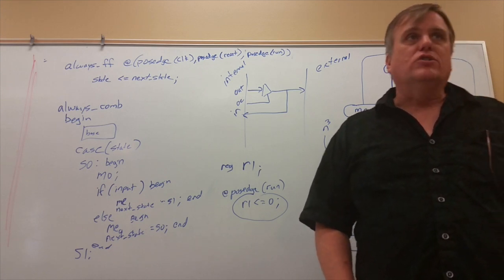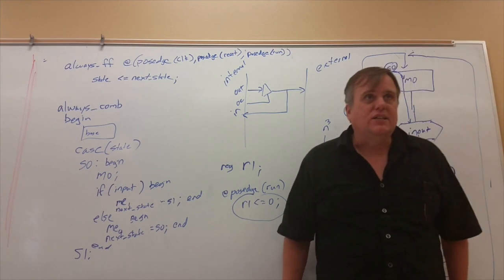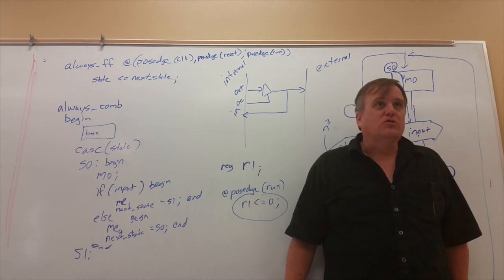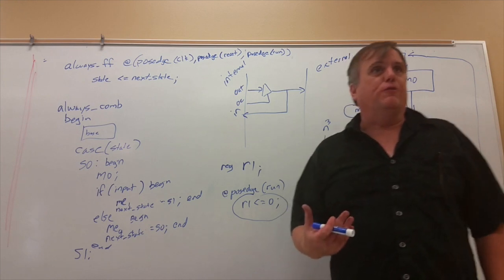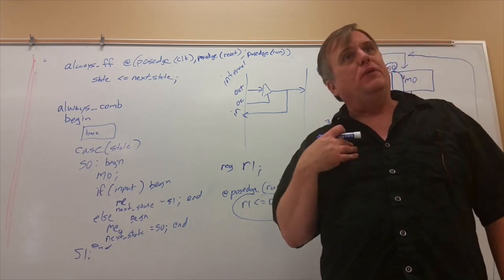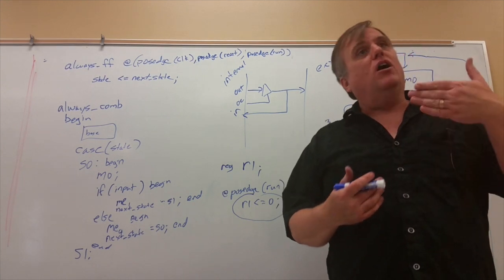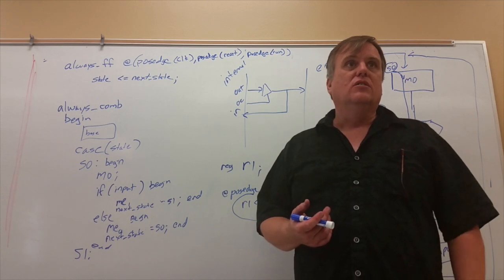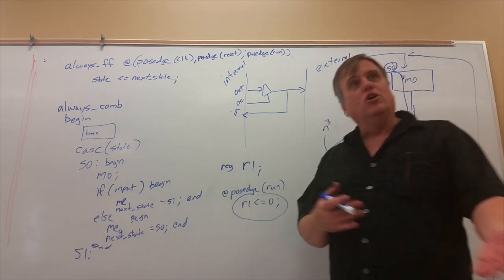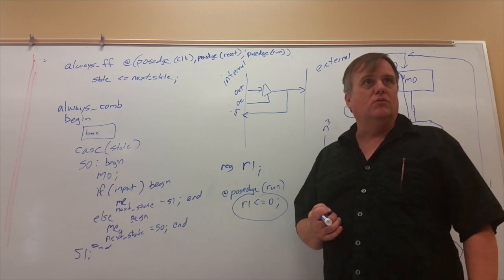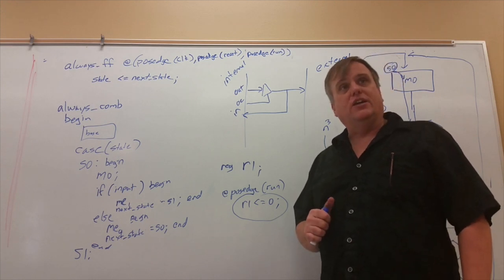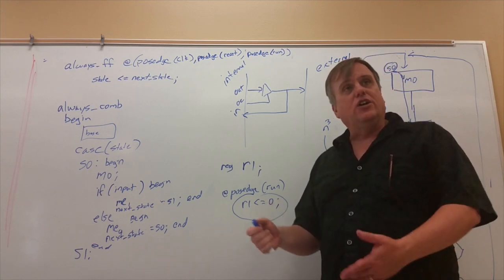So now you have to say, what is your tool going to infer? Technically, that tool should not infer something, it should flag you. Yeah, but they will sometimes infer, right? I can write something to infer, right? It's possible for me to say, any of our FPGAs do have an initial boot period where they load things in. So they could decide to infer, load from my external ROM. Oh, you mean the same way they can make that initialize RAM inference? They could say, infer a clear at the start.